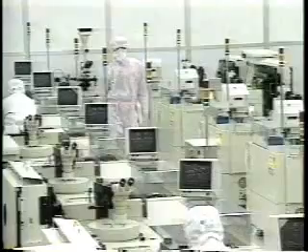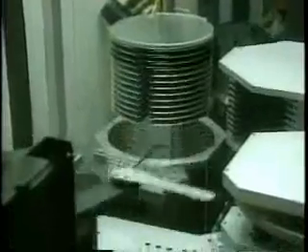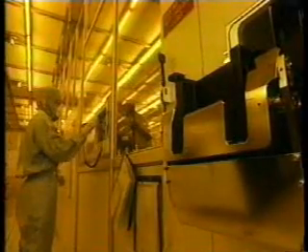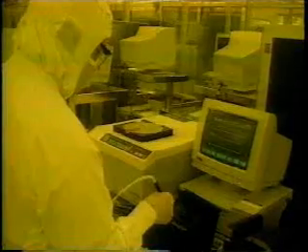One important aspect of understanding the cost of the product is to understand the cost buildup of the product as it flows through our factories. The cost of a product very early is just basically the raw materials and a low amount of labor content of a wafer as it comes into the factory, a wafer that may cost $40 for the raw substrate and has gone through 1 or 2 mask steps. Again, the cost we've invested at that point is relatively low. After that wafer has been through the wafer fab process and been through 20 or more mask steps, we have upwards of $500 invested in that.